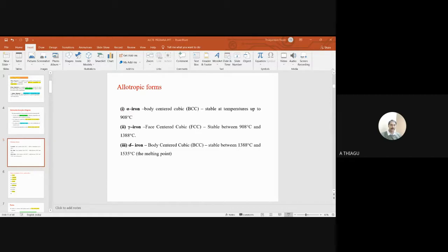The structure looks like upper bainite. In lower bainite, it is a low temperature, around 300 to 400. At this temperature, the transformation happens, so we can call it lower bainite. So upper bainite or lower bainite. Please remember these two technical terms: higher temperature and lower temperature transformation, because they may ask questions, MCQ type. Okay, so these are the microstructures of different materials.